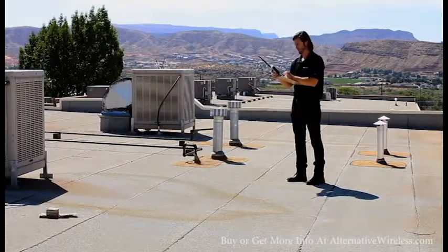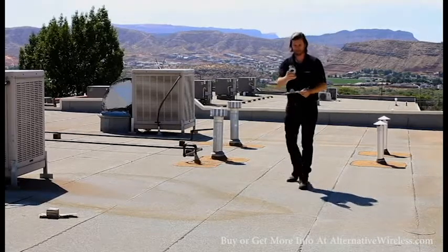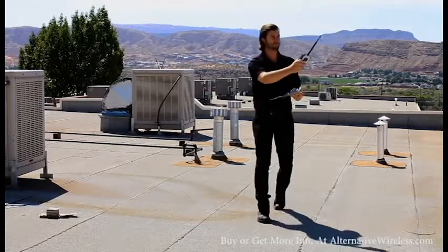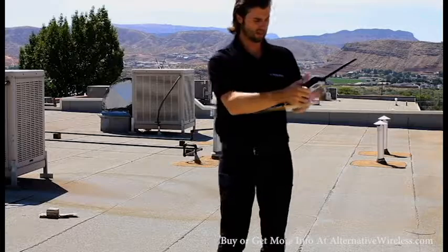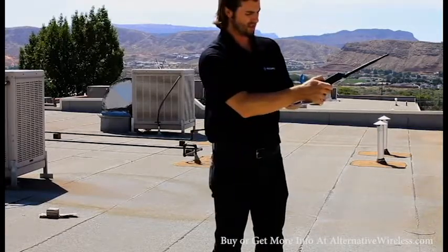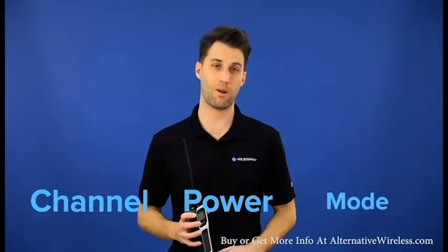When taking cell signal strength readings, you want to take your readings in the locations where the donor antenna will be mounted. The goal is to determine how much signal will be available for the amplifier, so accurate location reading is critical. The best way to get an overall picture of the signal strength at a site is to put your signal meter into channel power mode.